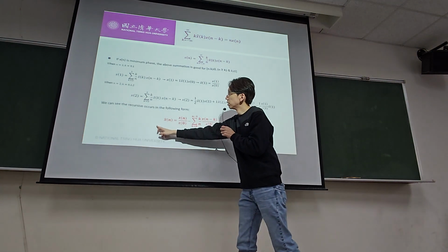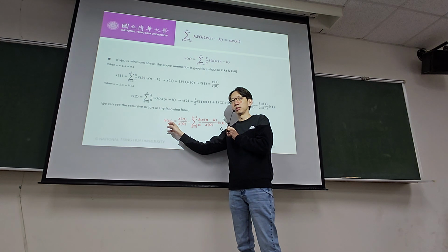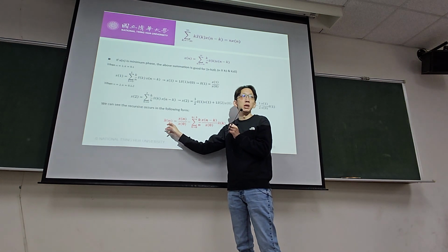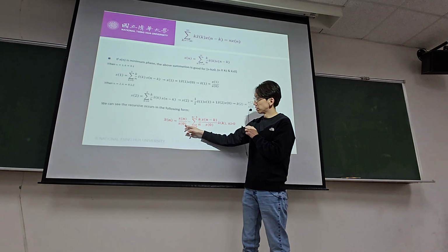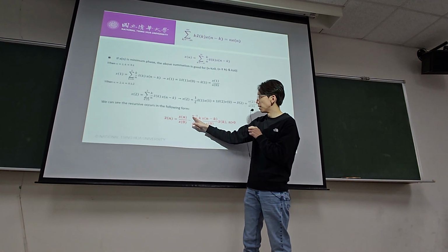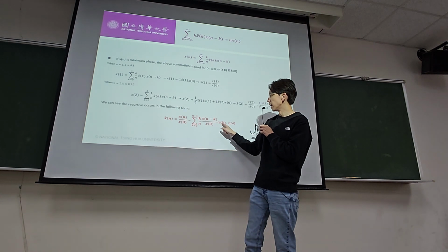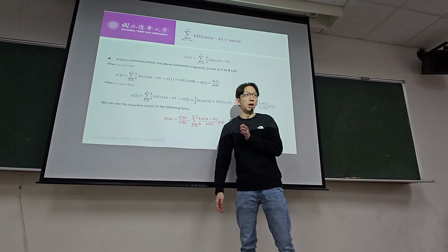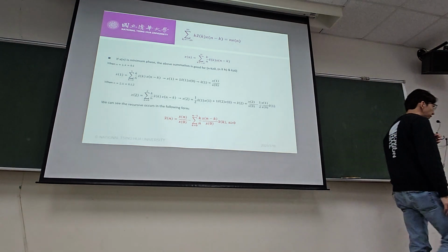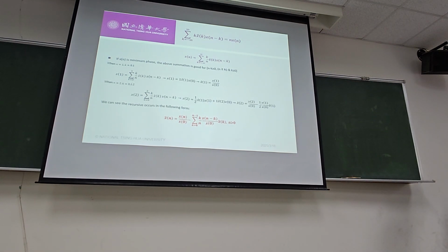So this recursion formula essentially can be written as this: x hat of n, right? The cepstrum coefficient of the minimum phase signal equals xn divided by x0 minus the sum over k from 0 to n minus 1 of k divided by n, xn minus k, divided by x0, times x hat of k, and n has to be greater than 0. Then iteratively, we can compute all the coefficients of the complex cepstrum.